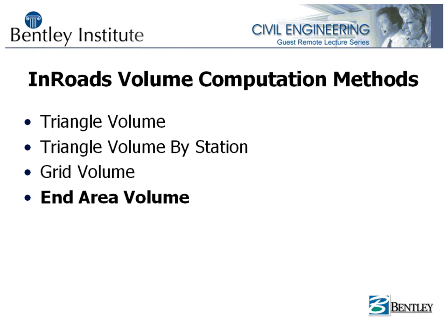InRoads has a few different methods for computing volumes. There's the triangle volume tool, the triangle volume by station tool, the grid volume, and finally the one we want to look at, which is the end area volume tool. I don't want to spend a lot of time looking at these other tools. I want you to be aware that they exist, and that's about it for this presentation.